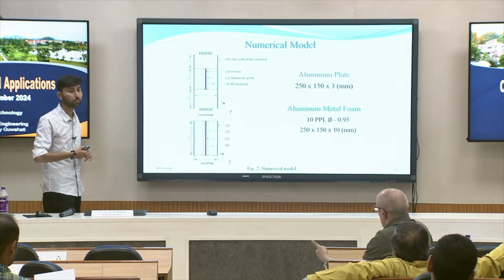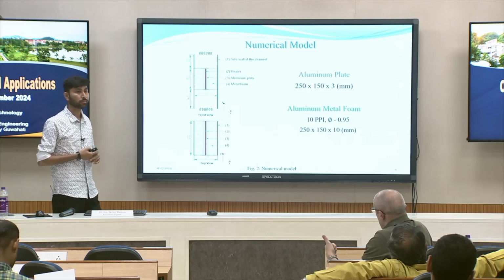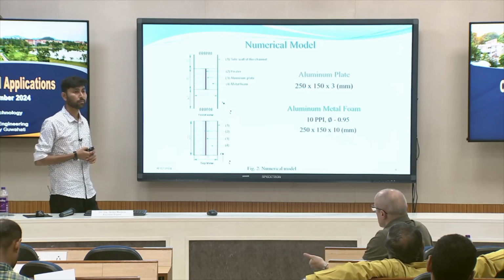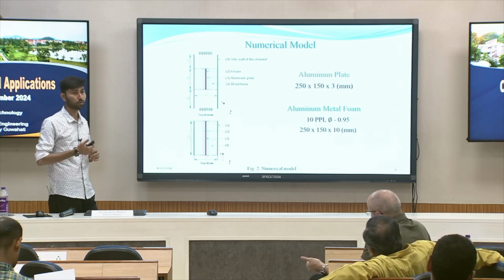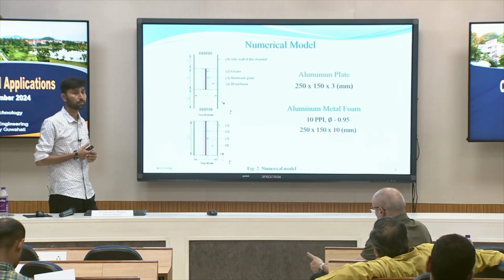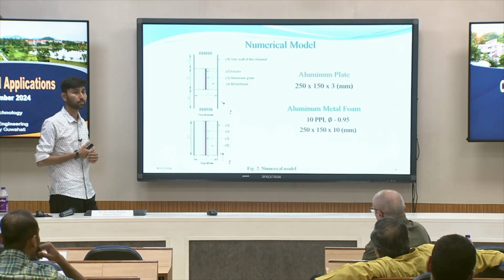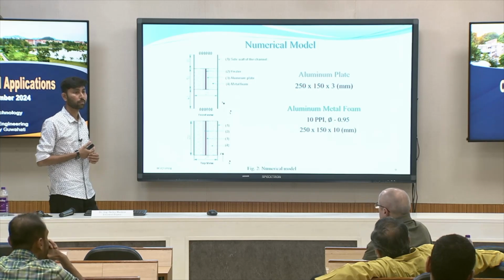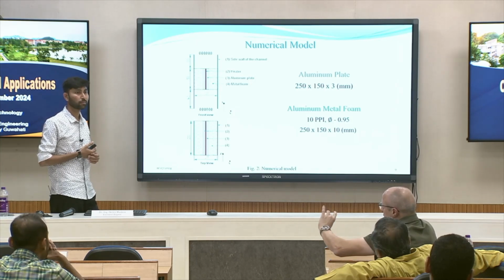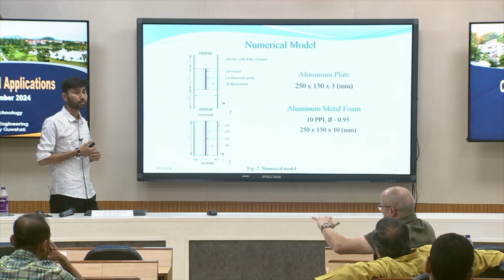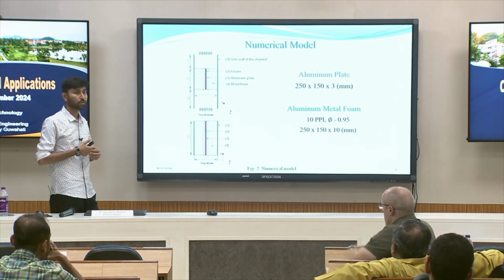So you have flow resistance on the one hand, which you have to optimize, and you have to optimize the heat transfer to the gas phase. Then finally, concerning your burner, is it a mild combustion process? That means, is the flame inside the porous structure, or is the porous structure used to laminarize the flow, and the flame is above the porous structure?